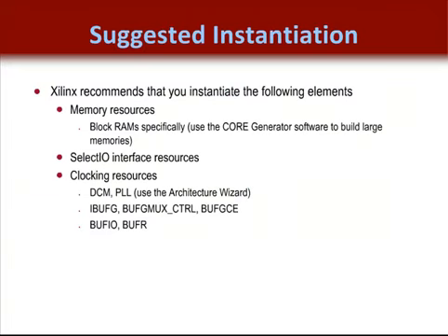Now most designers are instantiating memory resources, I/O standards, including SerDes functionality, and clocking resources on every design. That is because there is just so much flexibility with these FPGA architectures that the synthesis tools just can't build a tool that will infer all the possible configurations that a customer might use. So you're probably better off planning to instantiate these resources from the beginning.